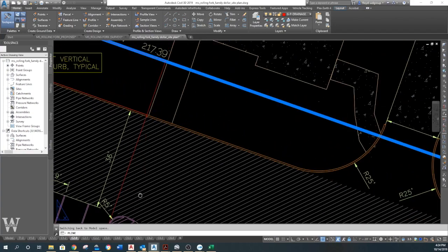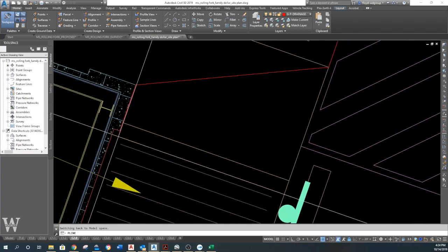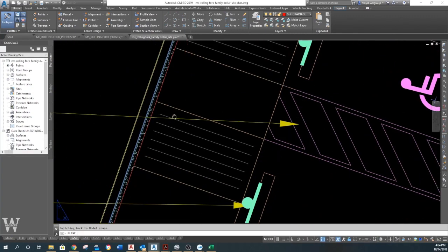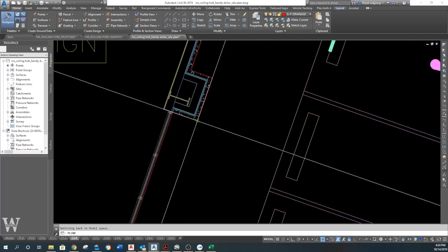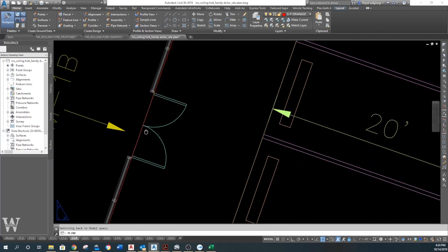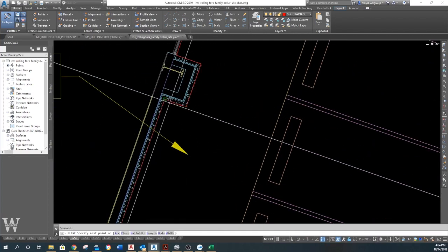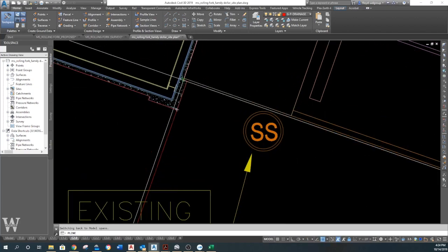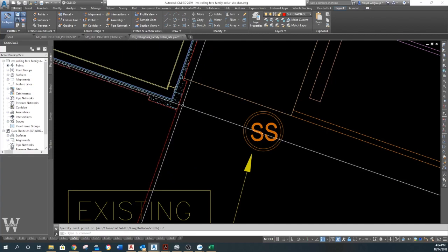But we can't do that here. So we have to do some manual stuff like we're drafting, but still better than rolling that kilometer around or taking a bunch of areas and squaring them off and adding a bunch of numbers together. We can just draw a polyline around the objects and find out what it is right there.